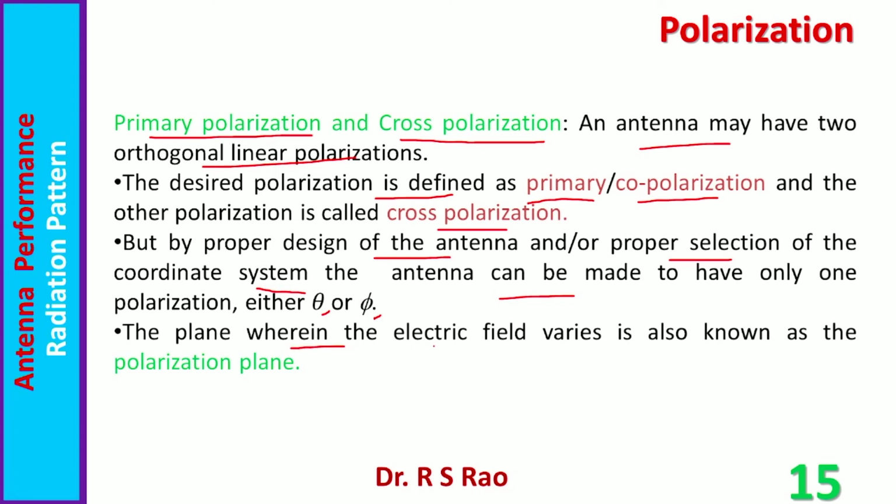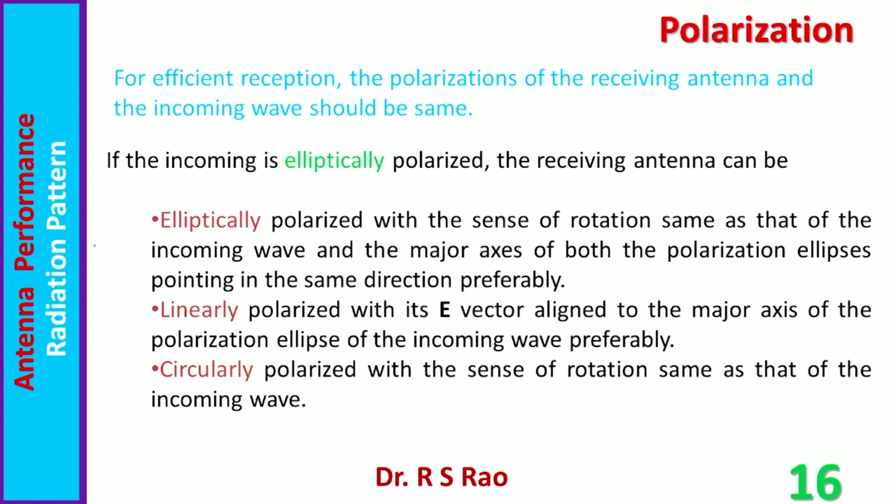The plane wherein the electric field varies is also known as the polarization plane. These are some of the terms we encounter frequently while studying antennas. Some more points regarding polarization's importance. For efficient reception, the polarization of the receiving antenna and the incoming wave should be the same. There should be a polarization match between the receiving antenna and the incoming wave. Both must have the same polarization, preferably.